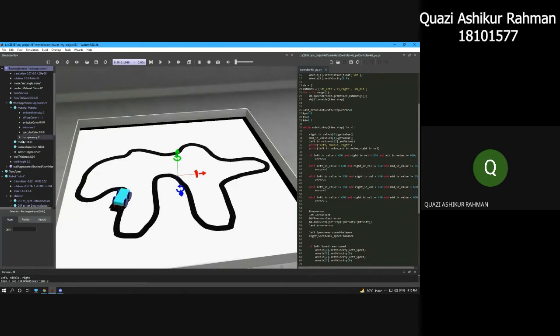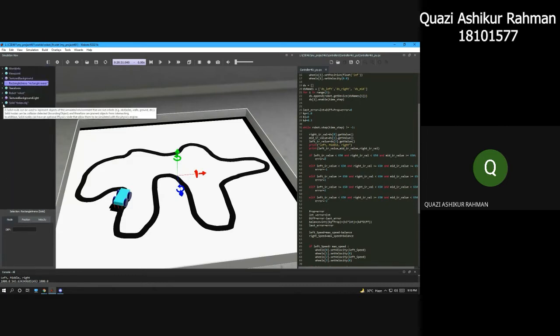Then for the line, we need to create our desired track, with the required left and right turns, in Autodesk Tinkercad. We will be adjusting the height over there for sure, because it was a bit too high for the environment that we were using. Then we will just export and import the 3D model object file in our environment.